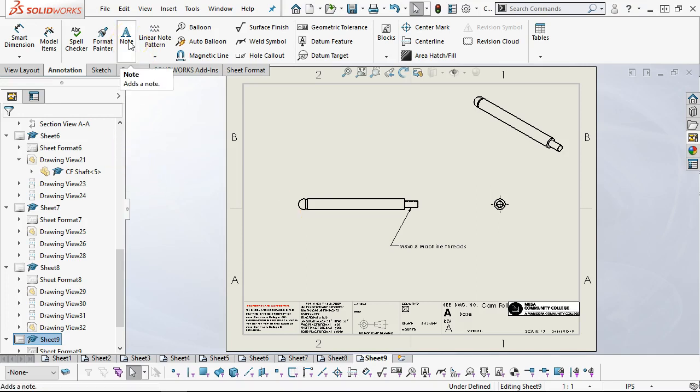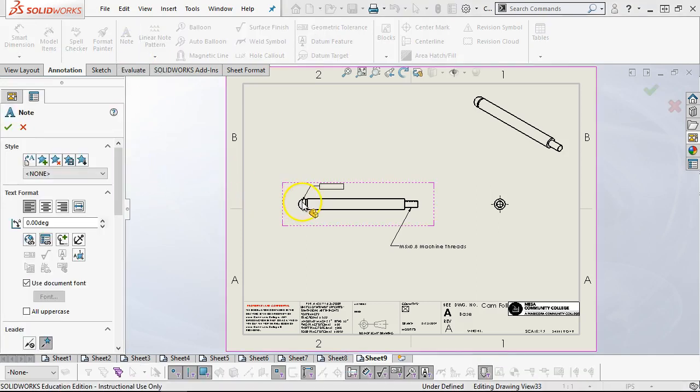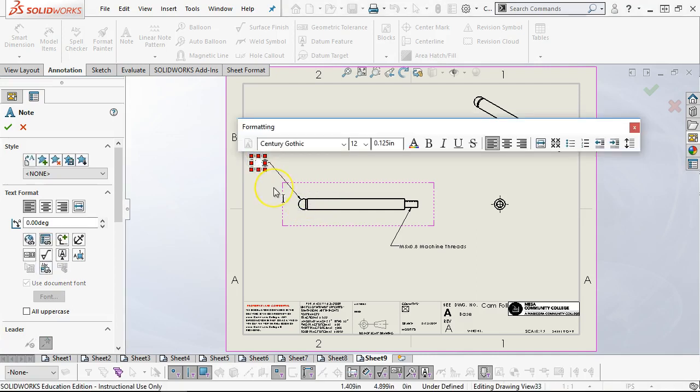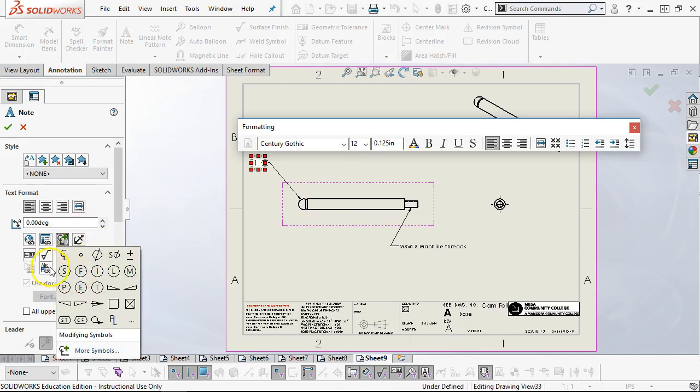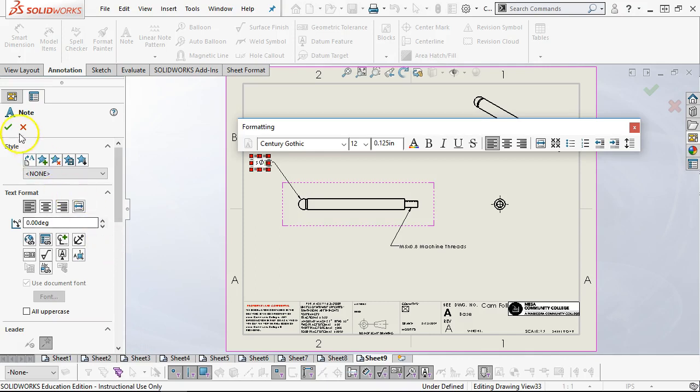So the one thing I wanted to throw out is the notation that when we place the dimension, whether we're putting it into the actual dimension or we need to pick up the symbol, then we can look down through here and let's see, that's the controlled continuous. All right, not seeing it. Oh, spherical diameter. All right, so I was thinking spherical radius, but that gives us the spherical diameter.